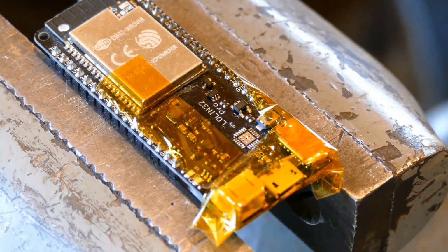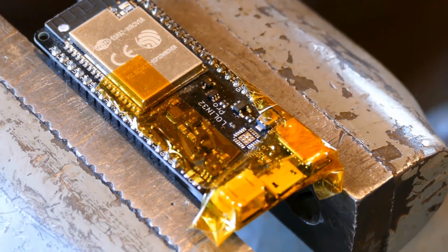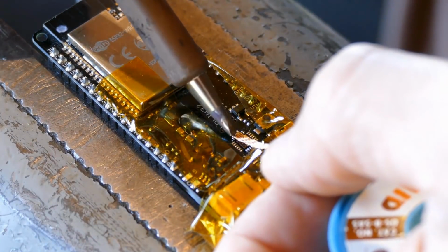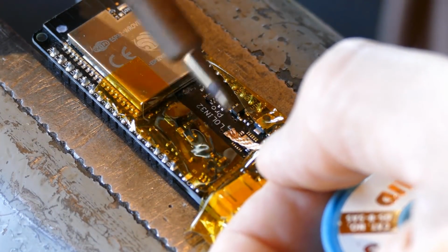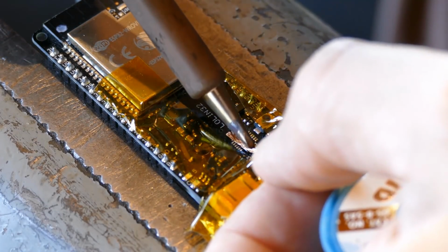Well, that works surprisingly well. The video is not sped up at all. The chip came right off with no damage to the pads and nothing else got disturbed. Soldering braid is used to clean up the solder residue. The tiny pads are fragile, so I like to drag my iron along the long axis of the pads as opposed to dragging across them.